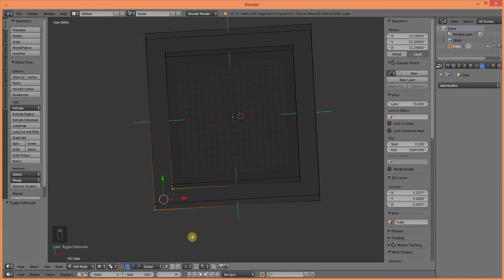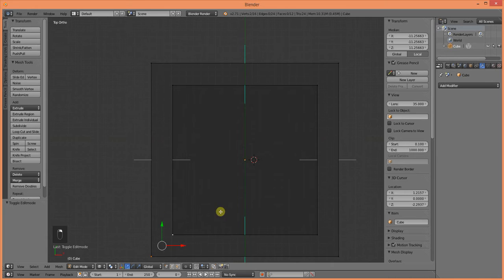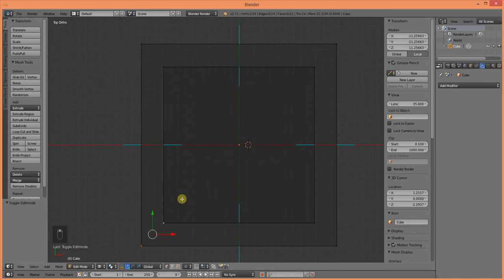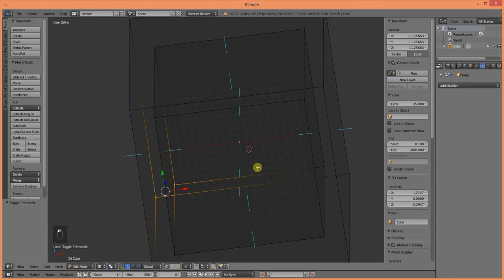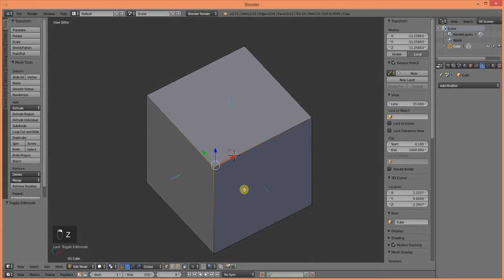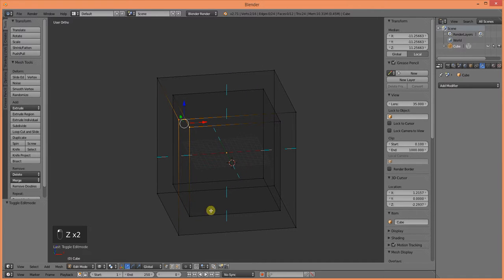Now one thing to look at, let's go in the overhead view right here. One thing to look at is the normals of the faces. You've got your normals facing outside all the way around the outside cube. Now the inside cube, all the faces are facing inside. Why is that? Well, that is the outside surface of the hollow area. So if I were to print this, then it will be printed with a hollow core.